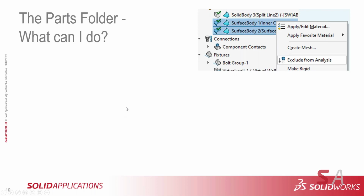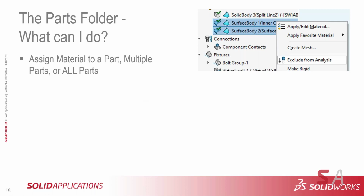So in the parts folder, what can I do? You can assign material to a part, to multiple parts, like you see here. I've got two parts selected, or all parts. Now, I say parts, and in simulation, they call them parts. They call it the parts folder, but a more accurate name for this would be the bodies folder. Because one of the things to remember is that SOLIDWORKS Simulation does not care if they're parts or if they're bodies in a multi-body solid part, or if they are surfaces. It just doesn't care. It sees them all essentially as bodies. As long as they're defined, it's happy.